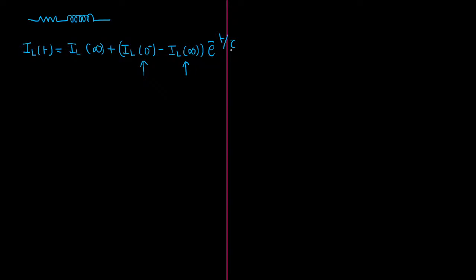You know how to calculate the time constant tau. Now find all these values, then substitute here. Then what should I do, sir? Then just check if the inductor is directly connected in series with the SCR, then I can say current flow through the inductor will be equal to the latching current only.